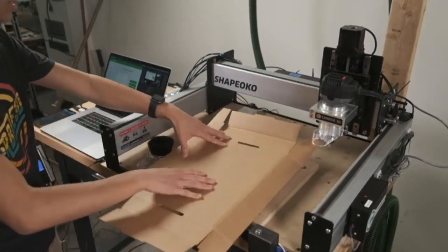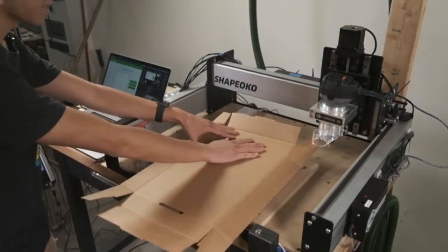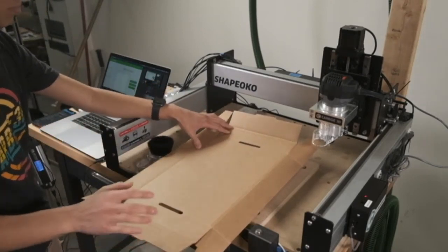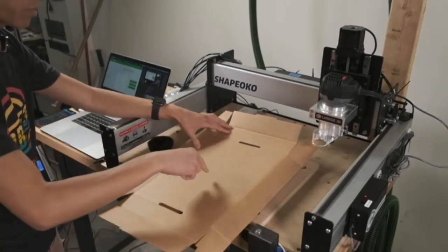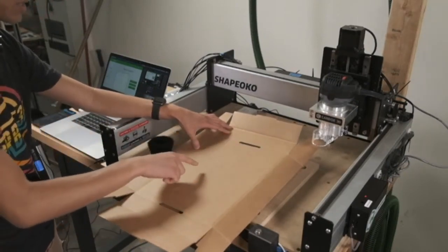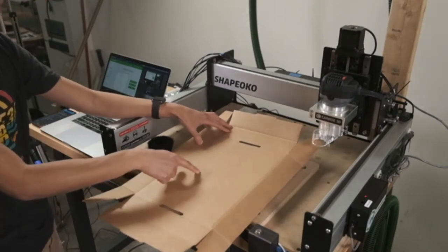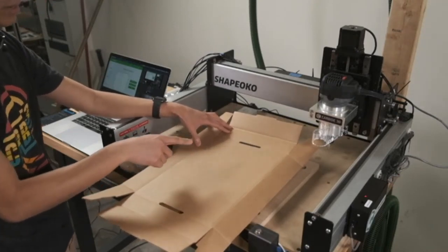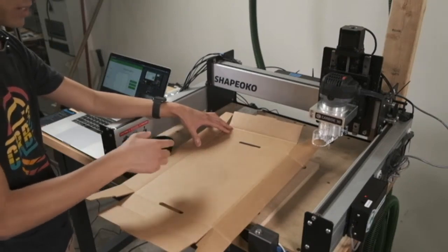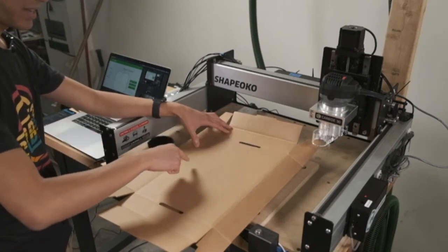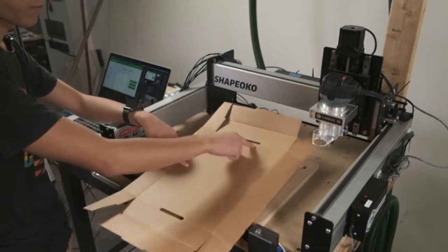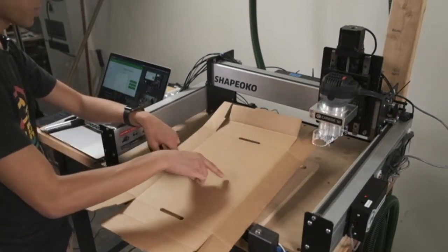So let's say you're trying to carve out someone's name, a giant bit of word art. You'd have to be able to separate the text that's over here from the text that's over here. And it's difficult to do this in Carbide Create because you can only cut on closed contours. So if you have, let's say an oval, you can't just stop the toolpath arbitrarily at a certain point halfway along that horseshoe shape.